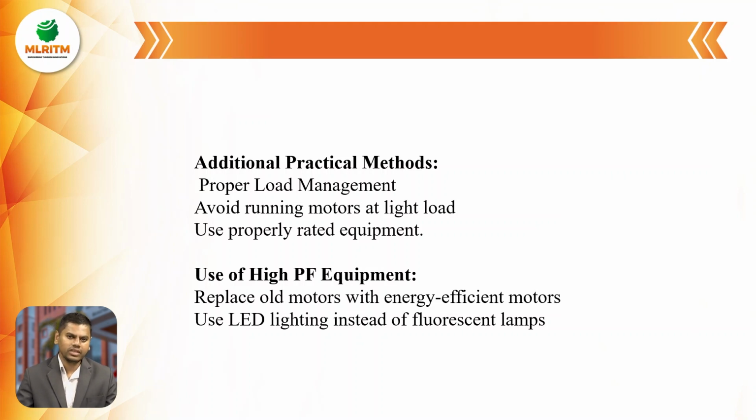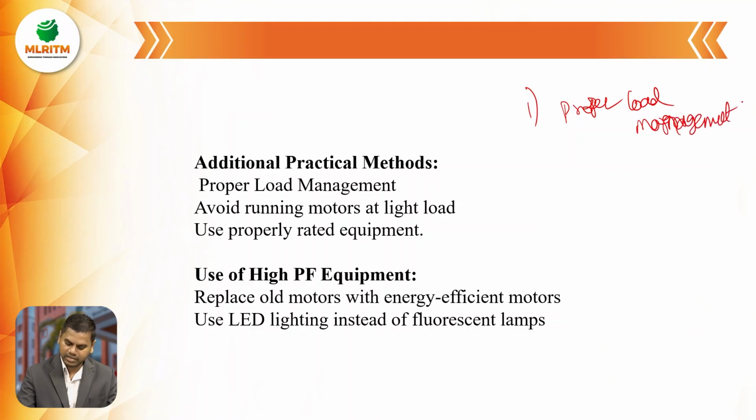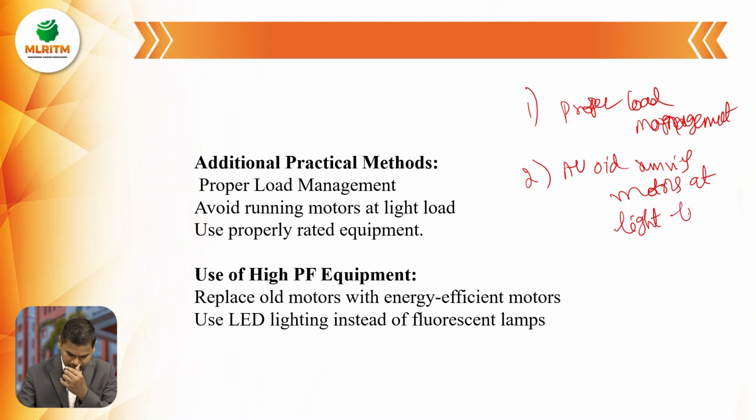Suppose we want additional practical methods. First one, proper load management. Second, avoid running motors at light load.